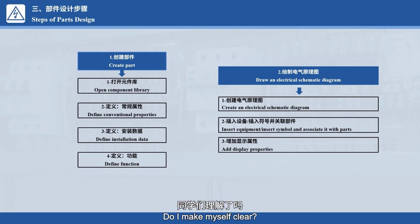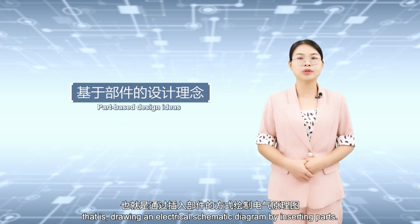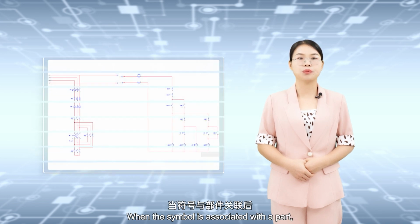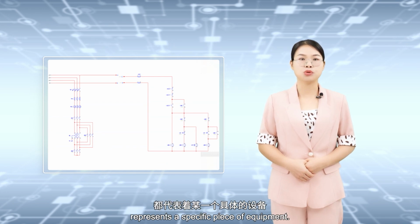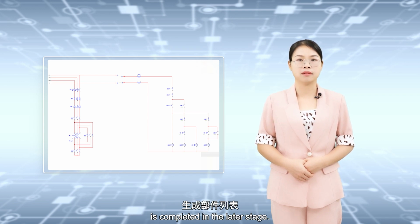Do I make myself clear? In this lesson, we focus on the concept of part-based design. That is, drawing an electrical schematic diagram by inserting parts. A part is a symbol with product information. When the symbol is associated with a part, each component symbol we see on the drawing represents a specific piece of equipment. It helps generate a list of parts after the drawing is completed in the later stage.